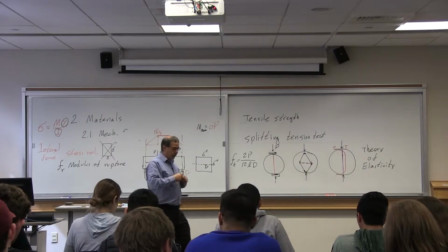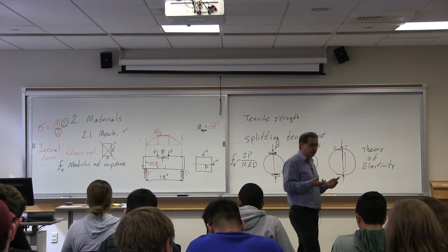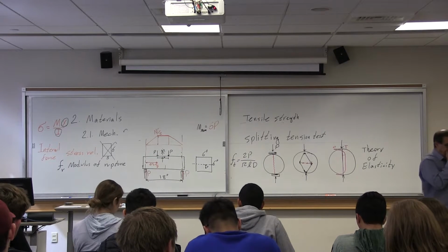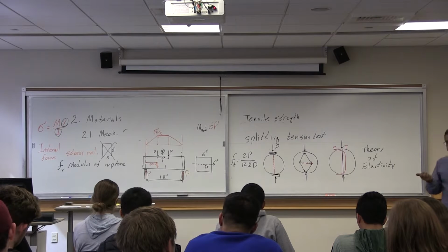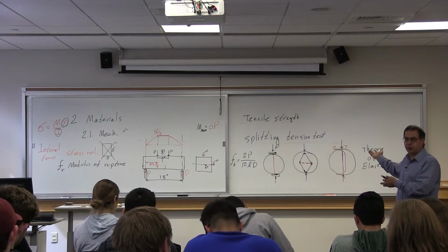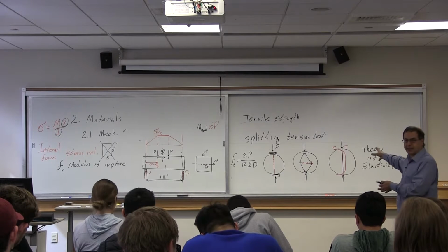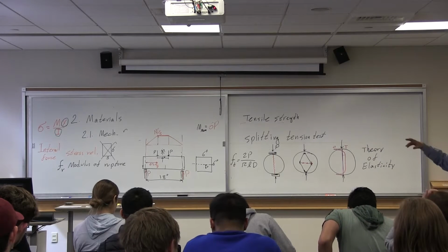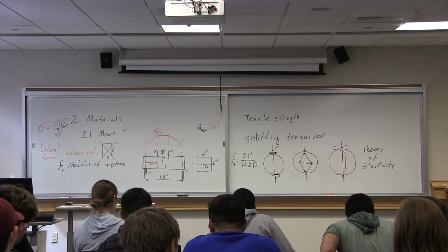It's kind of an unusual term for tensile strength, I think. But the reason I believe they used it was that tensile strength was already used. People were doing this test, and then the other test was developed. The alternative term they used was modulus of rupture.